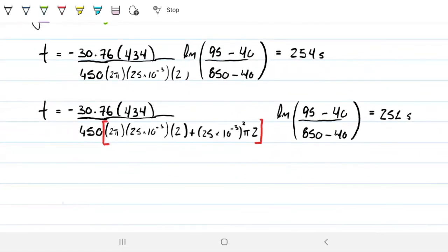Now, before anything else, let's check the units, because we need to be sure of the units every single time. This is mass in kilograms. This is my C sub P, which is given in joules per kilogram per Kelvin. This here is my H, the convective coefficient, which is given in watts per meter squared per Kelvin. Then we have the area, given in meters squared because we converted it all to meters.